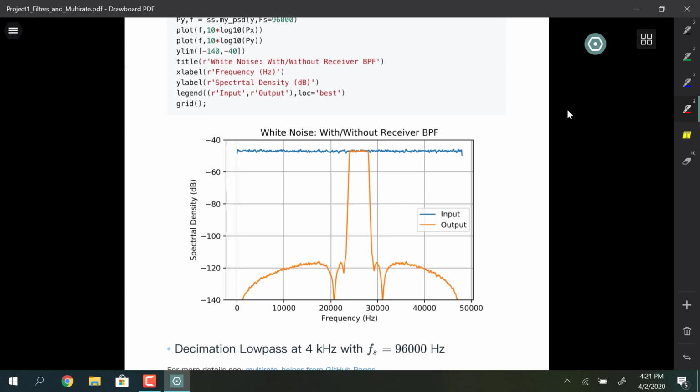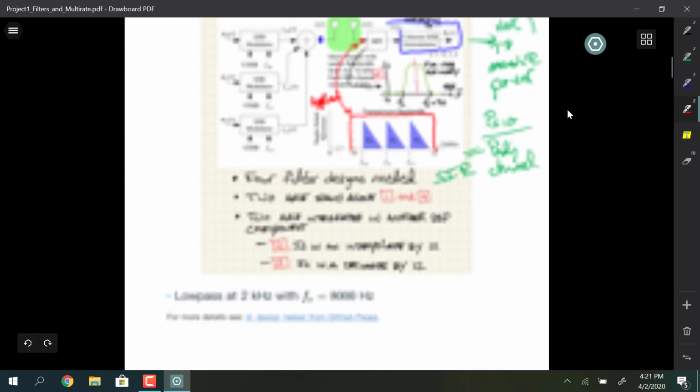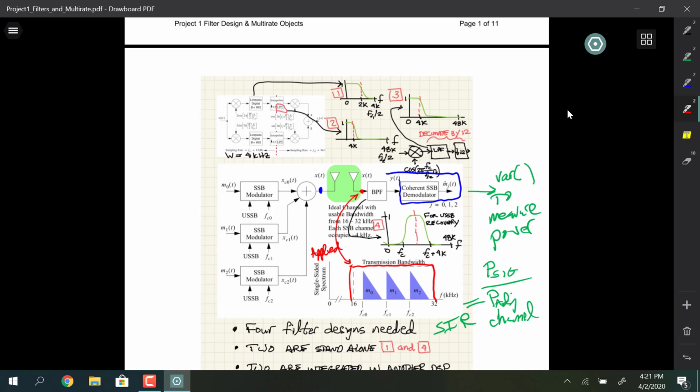If I go look in the block diagram, it kind of sits in between, but it sits right in front of it, so you can include it in there if you want to, right in the front. I'm trying to remember whether I had it just in the top level or in the D mod. Let's see. I have the bandpass filter in the D mod. And I call it a tunable bandpass filter. Yep, so it's in the function called SSB D mod, is where I have it located.